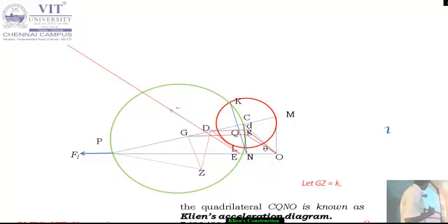So this is the inertia force of the connecting rod, that is the inertia force of the crank, and this is the inertia force of the piston, based on which you can calculate the torque value. So next what you have to do, you have to find out the normal force. The normal force will always be acting perpendicular to the piston. So from the piston, draw one line that gives you the normal force, Fn.